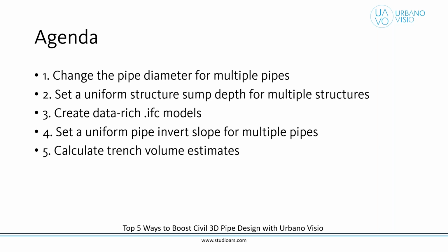I'm going to show you how to change the pipe diameter for multiple pipes at once, set a uniform structure sump depth for multiple structures, create IFC models which have data actually and not just the geometry.